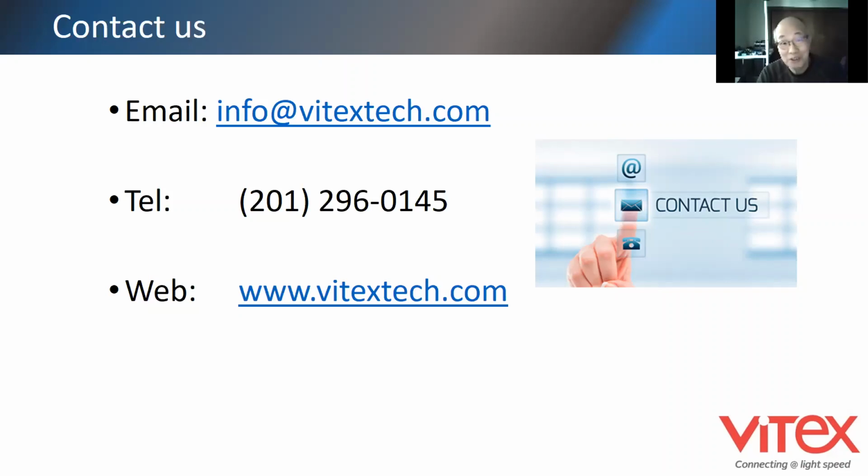That's a very good question. Usually this number is fixed, like a define for LOS on and off, right? Now, it can be a different function aside from the EEPROM table. The EEPROM table tells you how to turn it on and off, but if the level is variable, yes, it can be, if the limiting amplifier I2C allows you to change the set points.